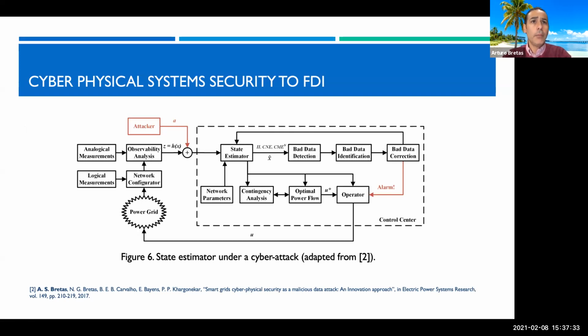So the assumptions of the state estimator in place, which are currently used towards CPS security, are very strong, but they've been working fine for the conditions that they were supposed to. Of course, when one talks about the increased use of IT and OT in cyber physical security, then you have other challenges at hand. You might have an FDI attack, which is the acronym for false data injection, not only on analog measurements, but also on the models itself, or the system parameters of the model, or simultaneously in all of them. So then, of course, the solution in place, which was not designed for that, will suffer.